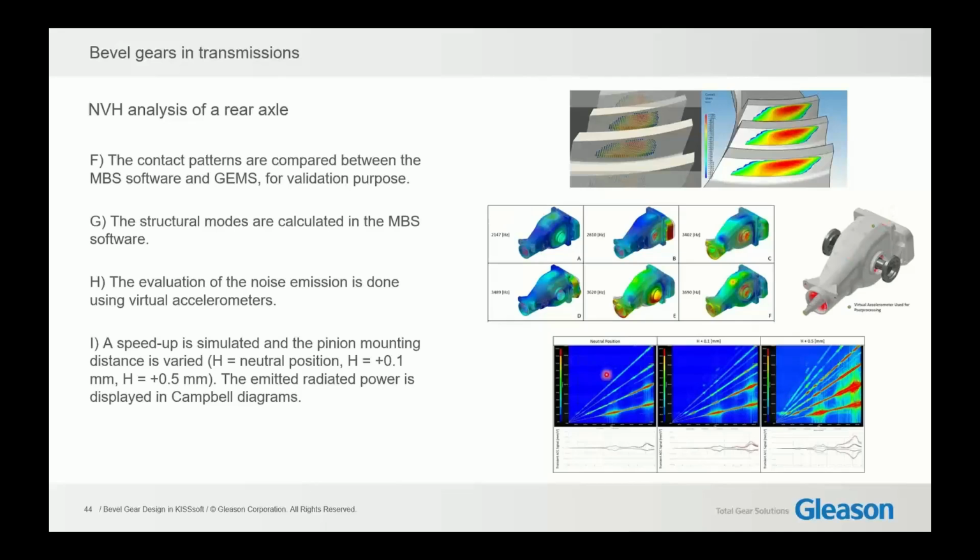What we did in this study then, we wanted to verify on this NVH analysis, and each of the Bevel Gear engineer knows that if the pinion is retracted with a mounting distance of 0.1 or even 0.5 millimeters, we will get different noise behavior of the gear pair. And this we did with the analysis as well.